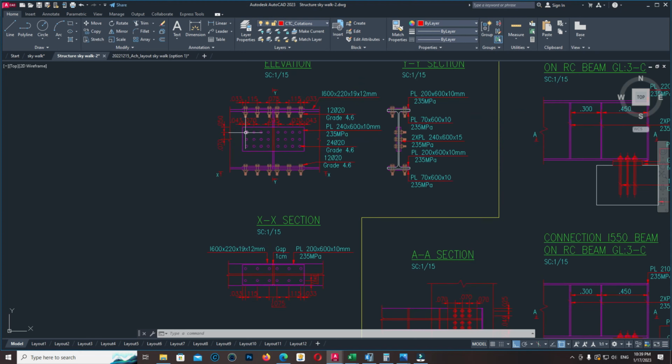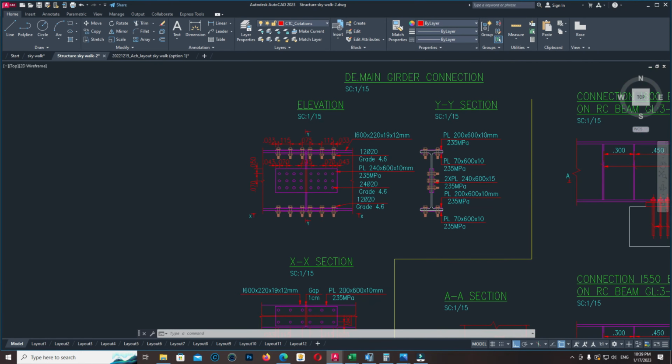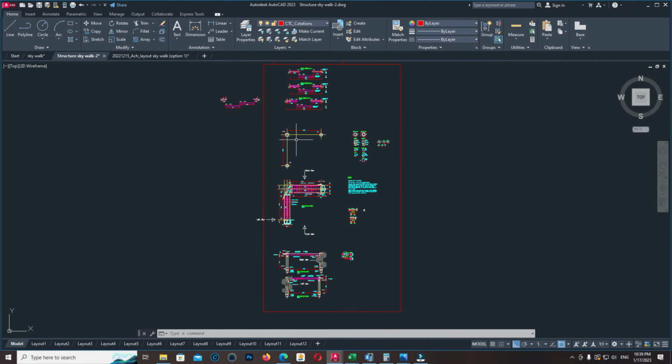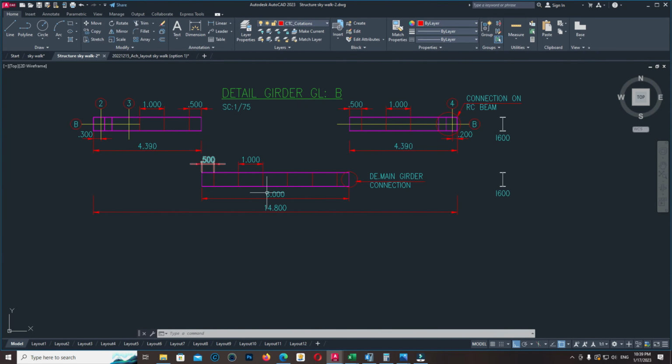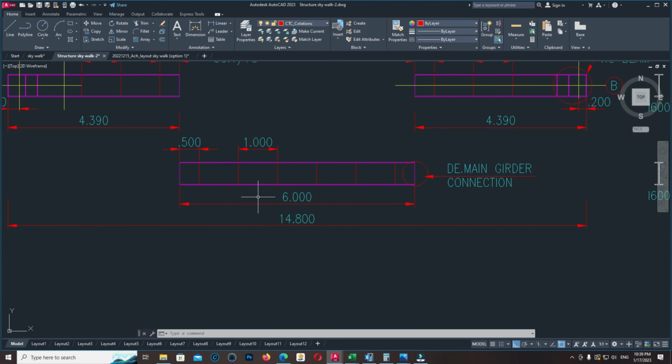For the steel connection, we use the moment connection designed at the maximum moment. Actually, we do not supply the connection at the maximum moment. We supply it in a different location. The maximum moment is at the middle span, but we supply it in segments. A segment is one piece of standard length of the beam.